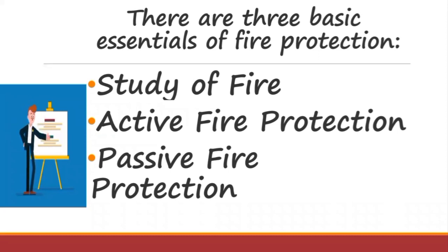Again, active fire protection requires action or motion in order to work efficiently. Fire and smoke alarms work. Firefighters work for the operation. While passive fire protection includes only the systems that compartmentalize a building through the use of fire resistance rated walls or floors.